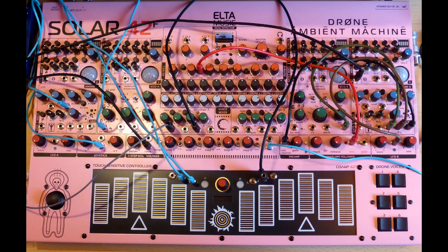I then realised the timing clock routing was unnecessary. It was only used to drive the sequencer, which in turn drives drone 5, so now I know the MPC 5V gates can trigger the drones. Why not bypass the sequencer and drive it directly from a 5-step pattern manually inserted into a CV track?